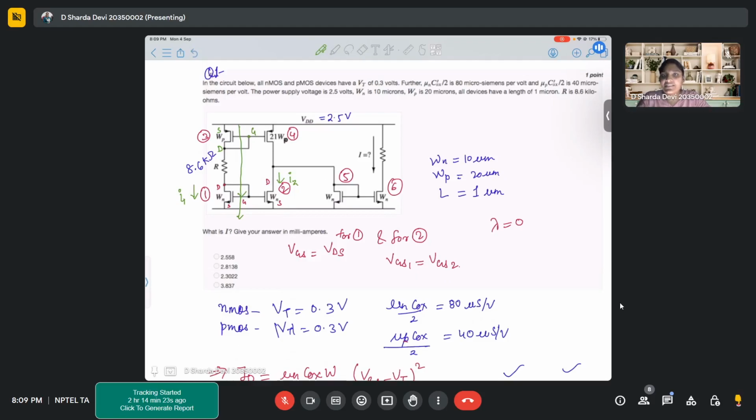Now let's say there is another resistor which comes in series in your MOSFET's path. You know that the same current is flowing through the resistor, and the drop across that resistor will increase. So the actual drop across your transistors will reduce. So those types of analysis you simply have to use. Otherwise, the concepts will remain the same, the formulas will remain the same. Just you have to see how to tackle these extra components, how are they appearing, how will you use and solve them. The concepts will remain the same.